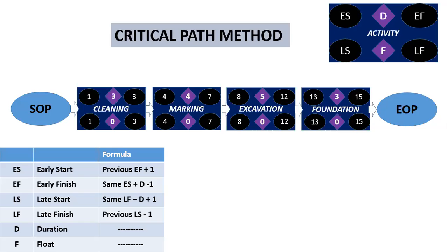Early start is previous early finish plus 1 day. Early finish is the same early start plus duration minus 1. Late start is the same late finish minus duration plus 1. Late finish is equal to the previous late start minus 1.